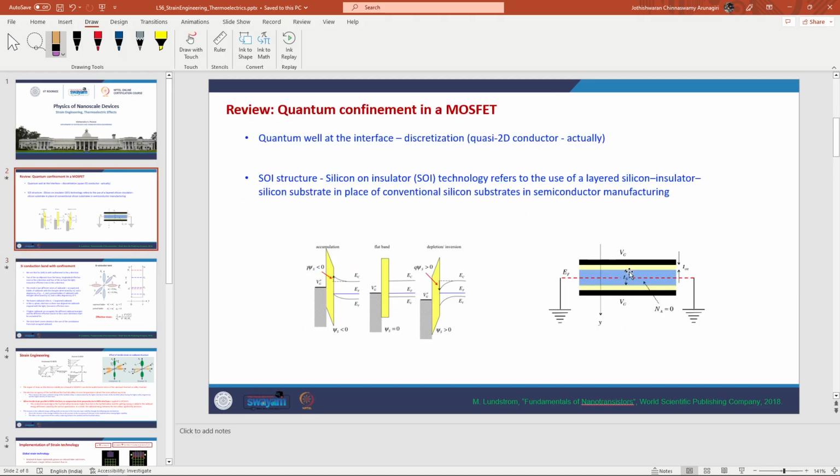So a device that leverages quantum confinement greatly to boost its properties is the double gate silicon on insulator MOSFET. As discussed in the previous weeks, alongside other benefits, this configuration also increases the shielding capabilities of this device. Therefore, effects such as DIBL are mitigated to a very great extent in these devices.